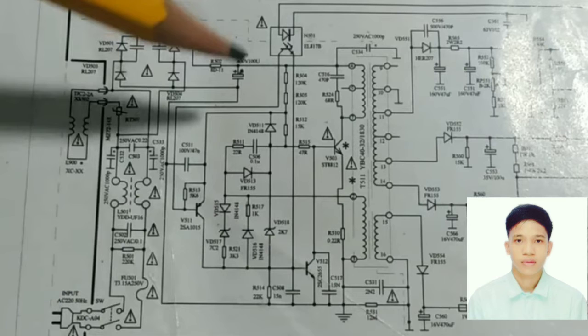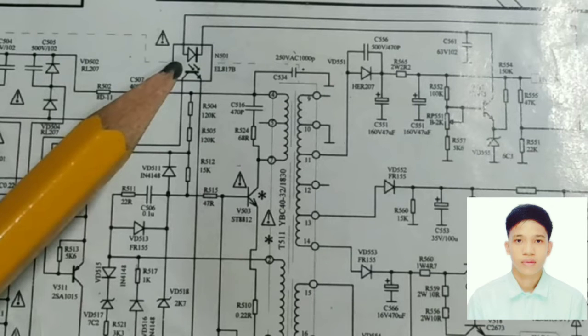And if there are secondary voltages, there is a distribution of voltages, but there will only be a continuous process of regulation if there is an operation of switching actions of the power supply through feedback. The feedback takes a voltage or signal from B plus to give signal for the secondary and it goes back to the regulator circuit, wherein it confirms that there is a power supply from B+. And if the opto-coupler is broken, we will no longer get a value of B+, or otherwise there is a shortage in the secondary circuit.